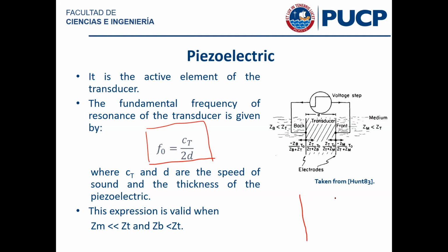Okay, and the reason for that is just like it's shown in here in the drawing, right? You have your piezo material, and this will have some sound speed. And let's say, just to simplify matters, we have this wall over here that is vibrating, right? So this will actually generate a wave that goes to the back, and then there's a wave that comes to the front like this.